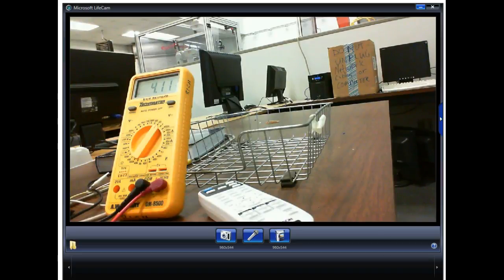We're not going to measure IE. We'd have to break the circuit. But we've calculated, right? Everybody okay? Yes or no? Going to come up here and measure voltage collector to emitter. That's next, right?